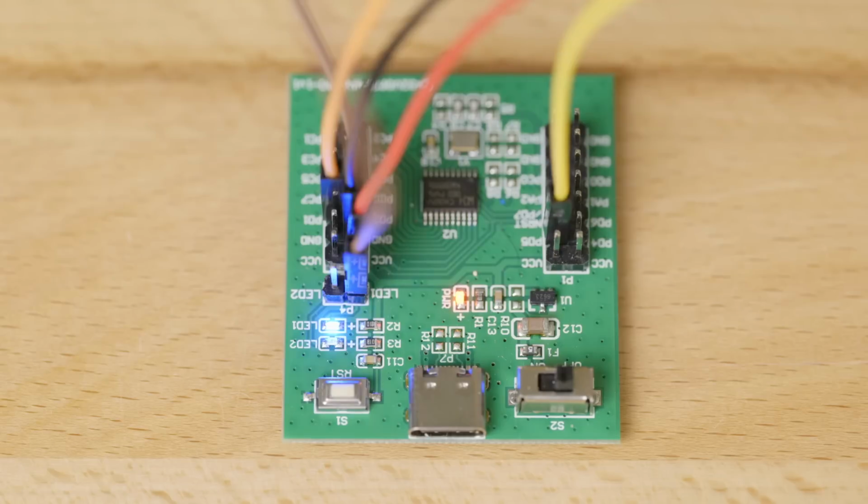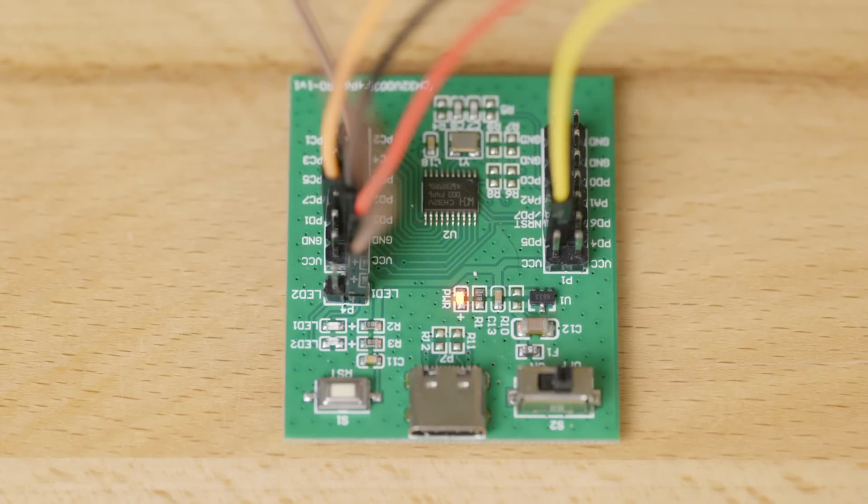The ADC is another good example. There is no code that just covers a single software start conversion, which is probably what most beginners, the ones who are reading the example code anyway, are trying to do. You can certainly piece together what you need from some of the more complicated examples, but I found this a bit odd. Regardless, I worked through this Blinky example reasonably quickly, and I got the board to blink its LED 500 milliseconds on, 500 milliseconds off, without much trouble. This was certainly faster than getting the PY32 running, even when you take into account updating the Link-E.